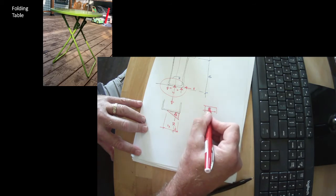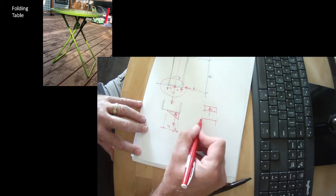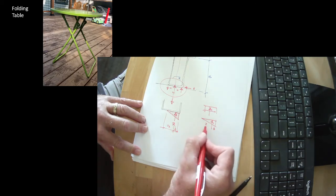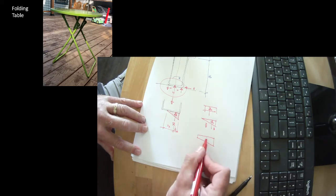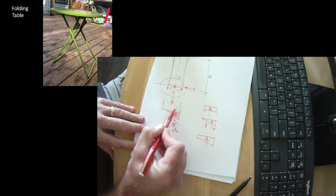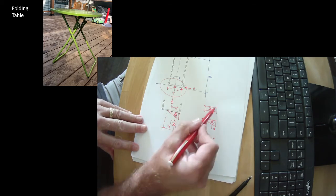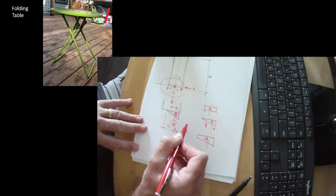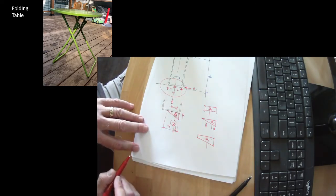We have the box condition where it's in the middle, the triangular condition where it's at the 1/3, 2/3, and we have the trapezoidal condition where it's somewhere in between. I calculate where the resultant lies, and then I know whether it's that condition or that condition or that condition based on where the resultant lies. And if the resultant is out here, our table is toppling over.